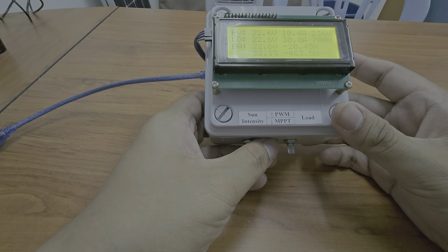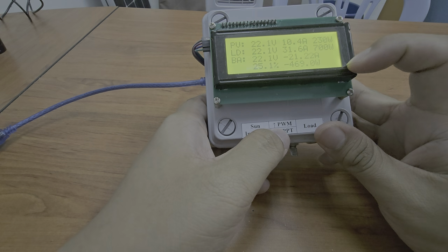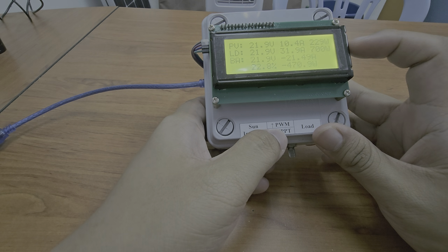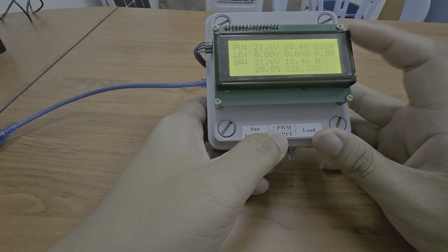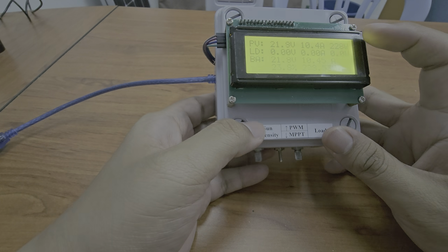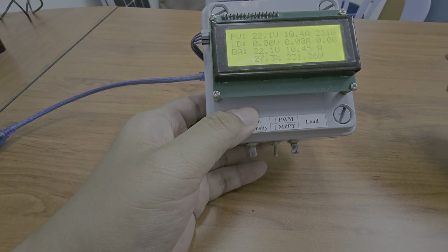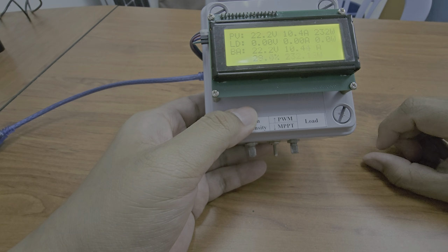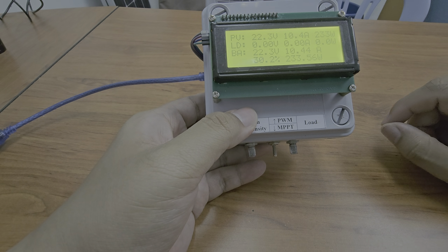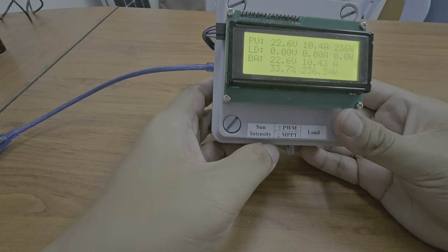For PWM and MPPT, the reconnect is usually the same. The difference is only when the battery is full. When the battery is full, the PWM starts to switch on and off like a PWM. So that's why it's called PWM probably. Basically it's connect and disconnect, connect and disconnect. So what happens if I use MPPT?